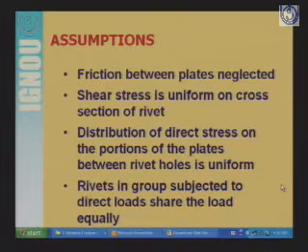Fourth assumption is rivets in a group subjected to direct load share the load equally. When there is more than one rivet in a connection and that connection is subjected to direct load, then in that condition we assume that the load is equally shared by all rivets.